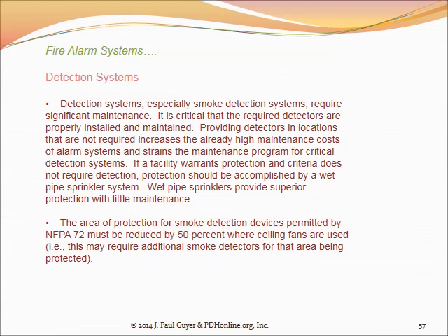The area to be protected by a smoke detection device is defined by NFPA 72, and that area must be reduced by 50% where ceiling fans are used. And this may, of course, require additional smoke detectors for the area being protected.